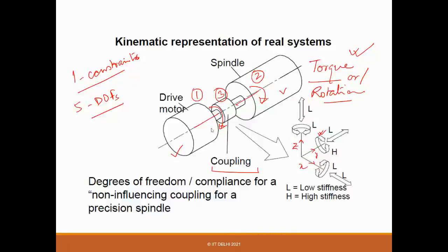That is like a flange coupling where you connect them through bolts, or you weld them. Many times people do that, but it's a really bad design, because it asks for complete alignment. The two axes should be completely aligned, and if they are two separate modules, that's simply not possible because of manufacturing or assembly errors.